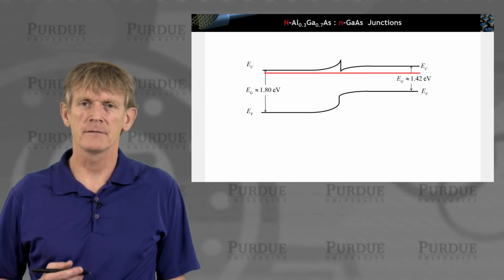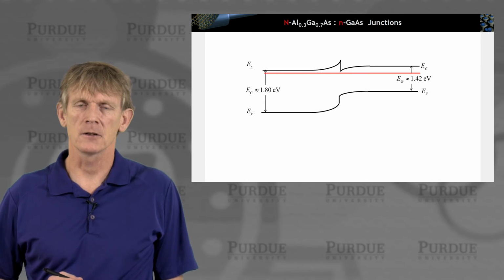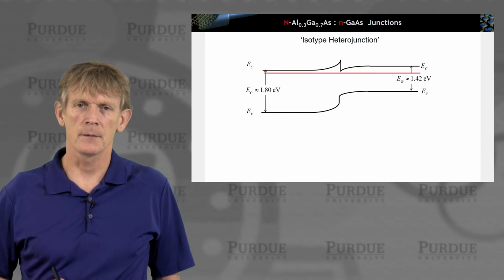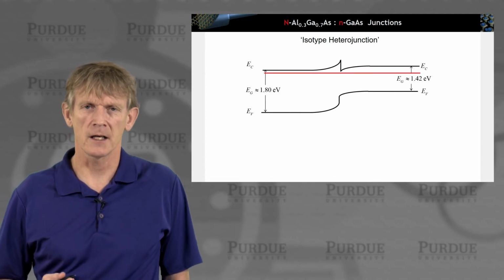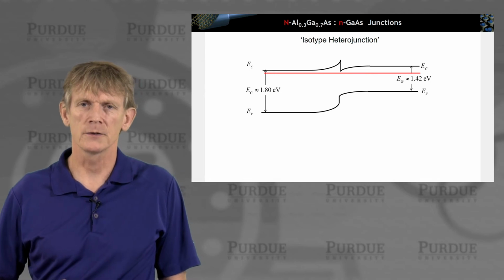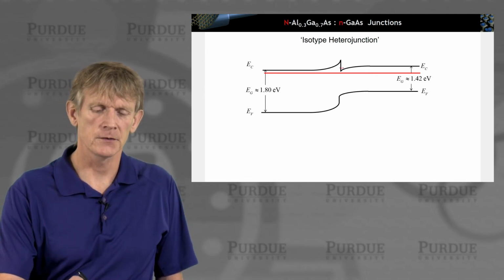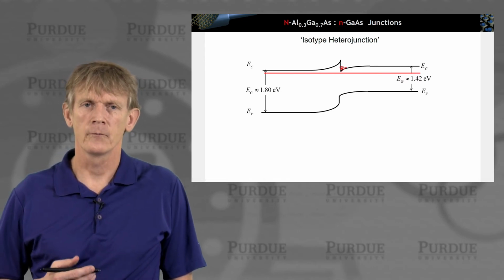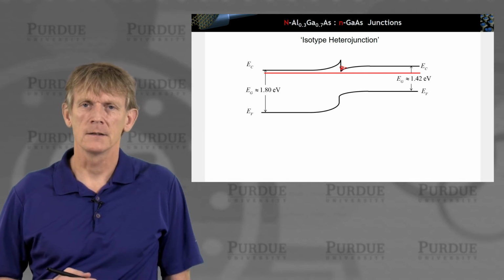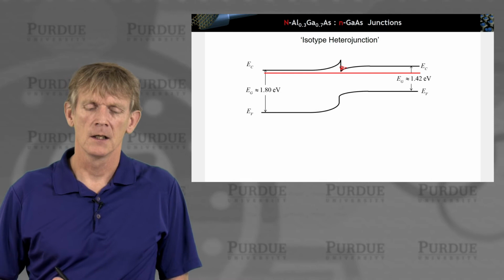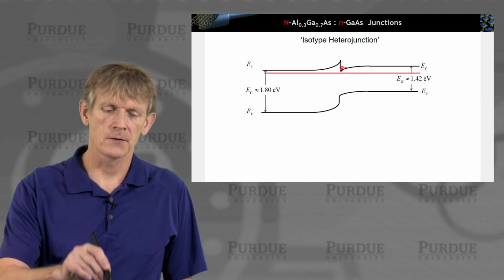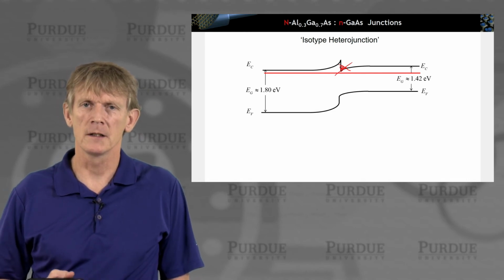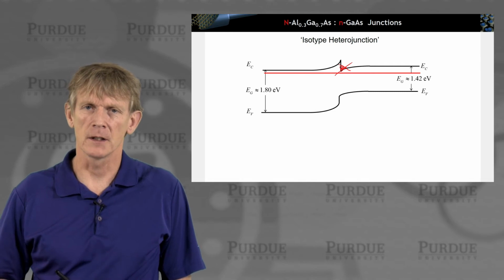And what you see is you have a notch that is building in the conduction band. So this is a junction that is an isotype heterojunction, meaning it has the same kind of carriers we're interested in by our choice of doping, but you can have pretty strong accumulation in this layer here. And this is a typical heterostructure where you might want to transport electrons, if you will, vertically in this channel here, where you induce carriers, and this is a high mobility transistor that you can build out of this, okay?